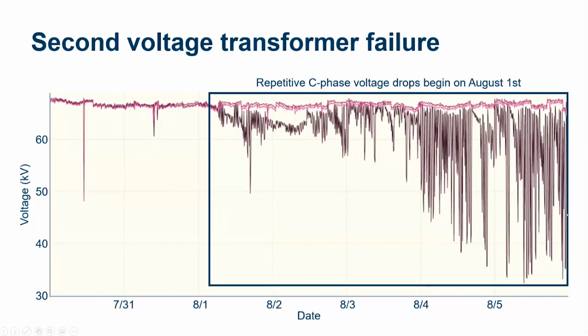While looking at this trend, we're looking at a week's worth of data at that data rate. We're dealing with several million data points on this trend, but given that our monitors only have a couple of thousand pixels for us to work with in terms of displaying information, we have an algorithm that goes through to make sure the worst case scenario is always displayed on the screen. So you go through a max-min algorithm and identify that.